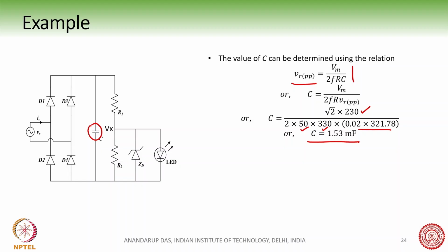Therefore people have come up with other solutions like the capacitive divider or something like that, which are also used commercially and are quite popular and very cheap. But we have shown you one way of making this kind of stiff DC voltage source, which can provide you with some amount of driving current.